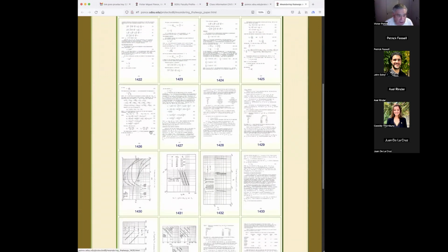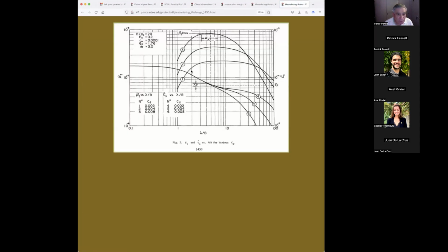And finally, at the end, we came up with a formula like this, which describes the celerity. This is for the celerity, and this is for celerity over here, celerity in the ordinates on the right, and the beta, which is the amplification factor of the small perturbations. And the beta came about 6 or 7, actually 5 or 6, somewhere in that range. That means that the ratio of the length of the wave to the width of the channel was going to be 5 or 6.